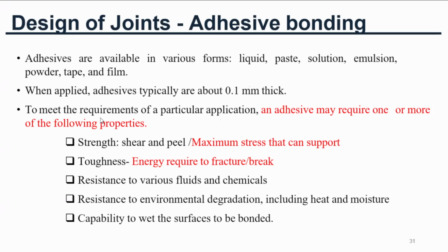When I apply adhesive, typically adhesive layers are about 0.5 millimeter thick. Okay, so 0.5 millimeter thick is what we commonly apply.